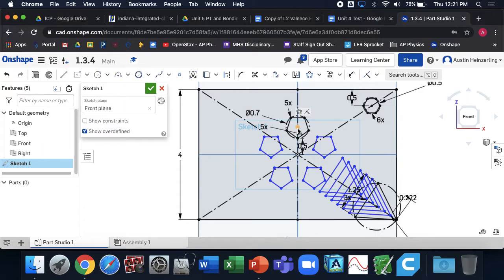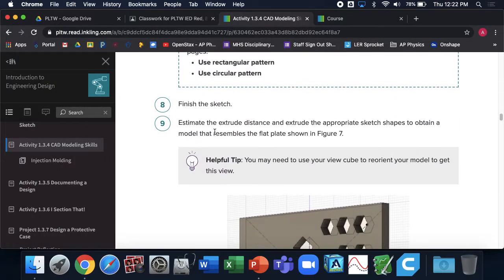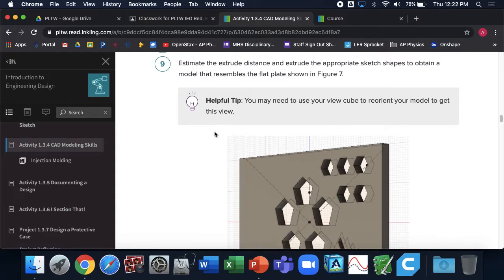Just leave it. Then take this, right? Yeah, 2. Then pull that down below. You want 2 rows. There you go. Then let go. Now if you go over here, see how it's got a green arrow? If you click, you're confirming what you just did and it'll place it. Alright, so what we're going to do is close that sketch. Now we're going to extrude.